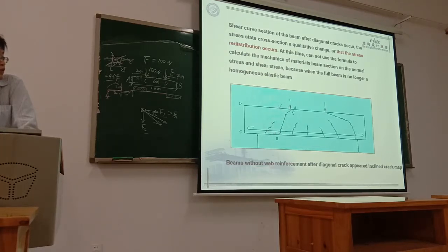All the tensile force is transferred to the reinforcement. At this stage, this reinforced concrete beam is no longer a homogeneous beam, so some formulas, such as Hooke's law, cannot be used to calculate the stress.